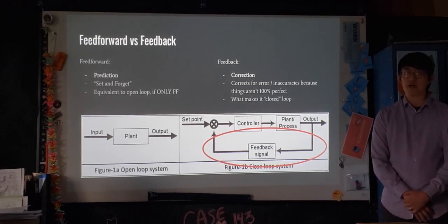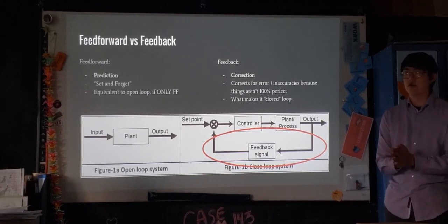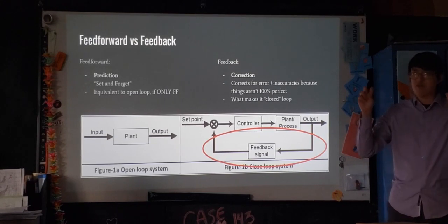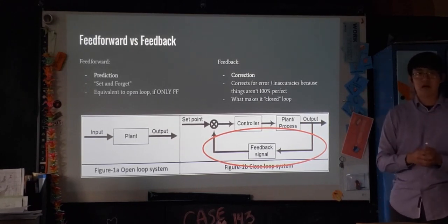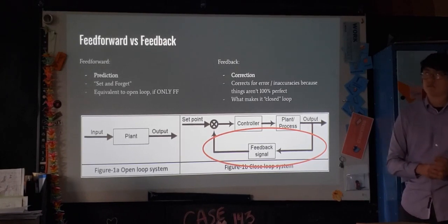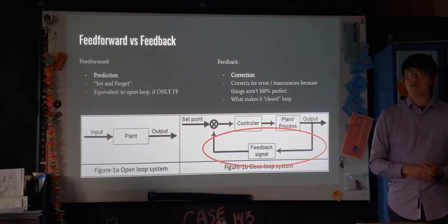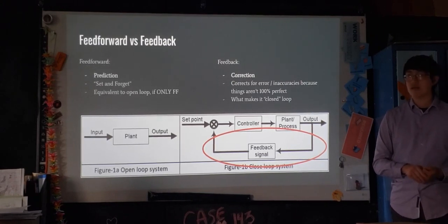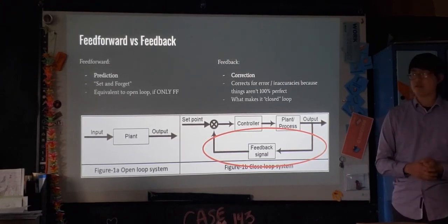Absolutely. That's absolutely right. You might have heard that we do something called characterizing the robot. We have the SysID program, which runs tests with the motors to try and figure out what good feed forward looks like. It's a little iffy, but it does an okay job.